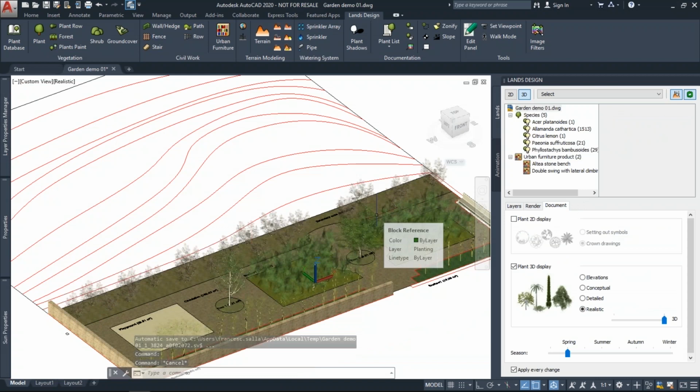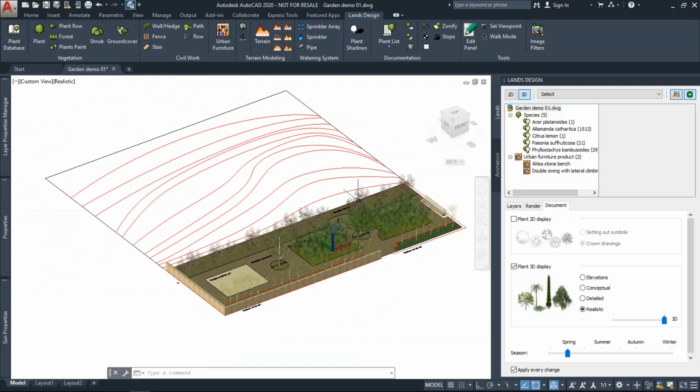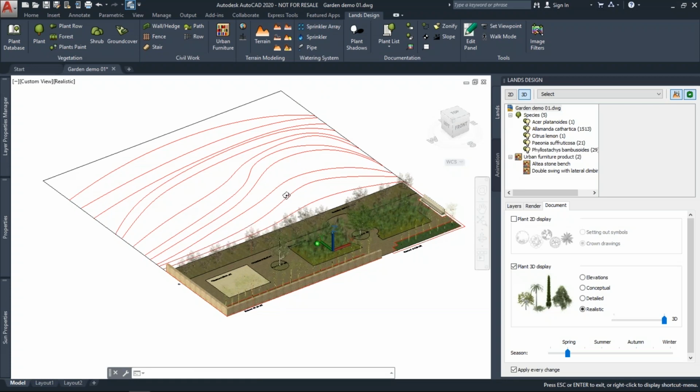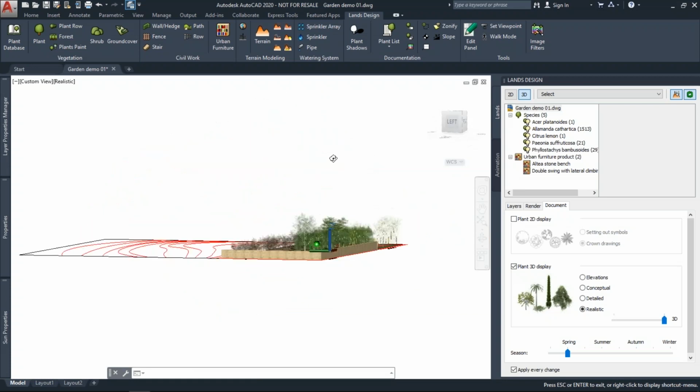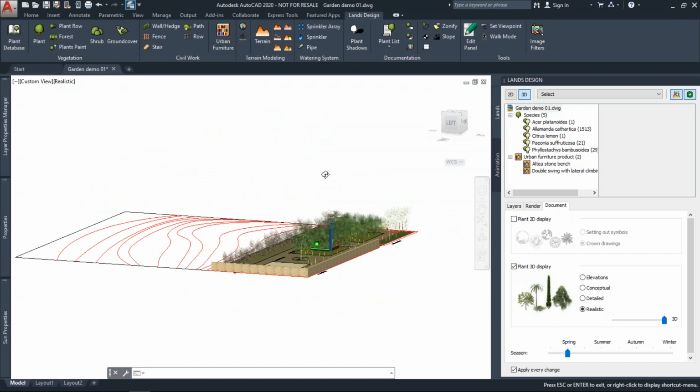Okay, first I would like to generate a terrain. Okay, so you will see how the plants are projected on top of the terrain as I do this. Well, there are different ways to generate terrains, as we have mentioned already. We can import them from the web, also from digital elevation model files, from curves or points in the 3D model space. So basically, it would be a common scenario to have all the contour lines just in a flat position in the same plane.